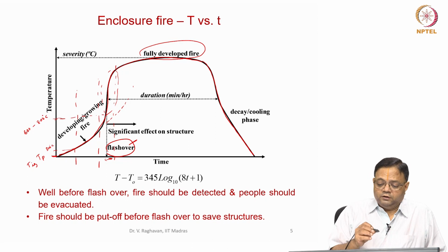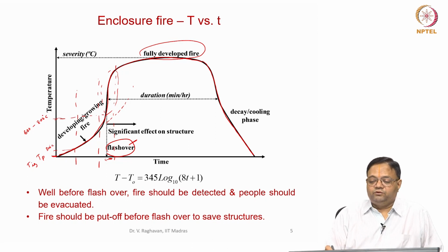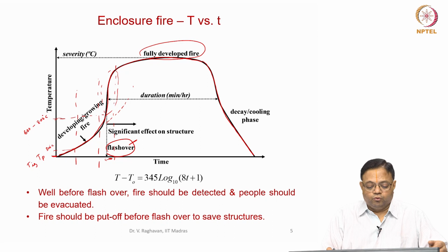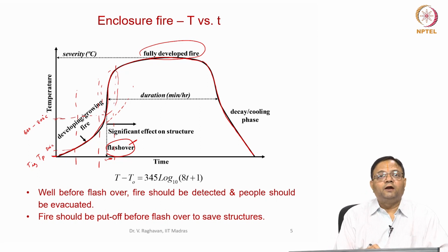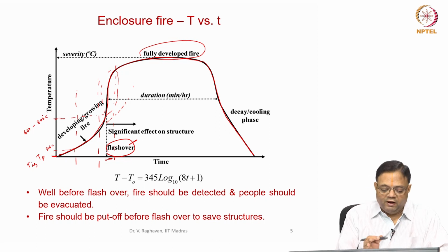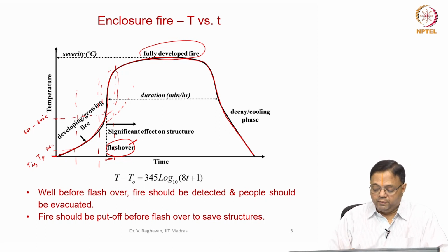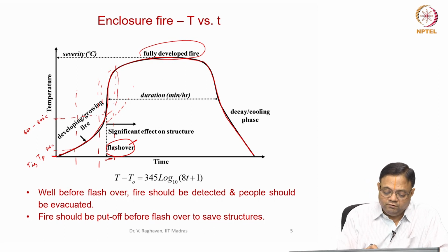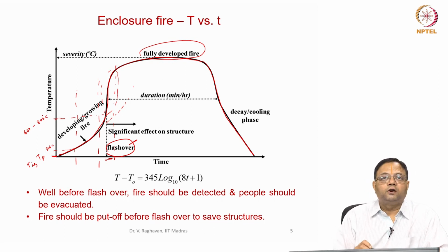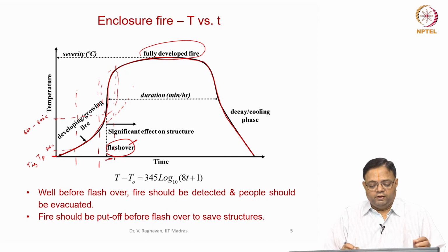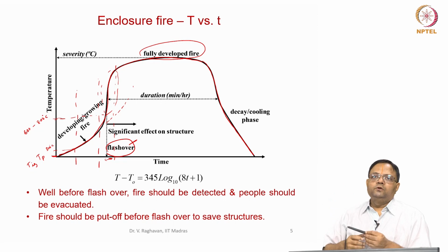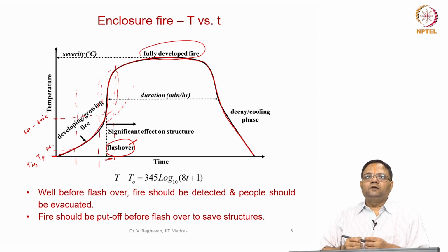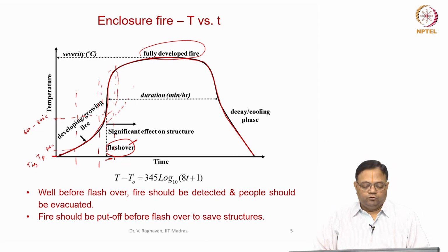Okay, so the intention of understanding these stages in a fire is to get the time required for the growth and, well within that time, evacuate the people. That is, the temperature should not exceed a particular value. So, see, for example, if the smoke layer goes to 200 degrees centigrade, it may trigger a sensor, and the sensor can trigger a sprinkler and so on.